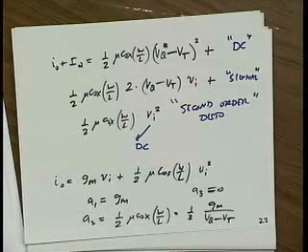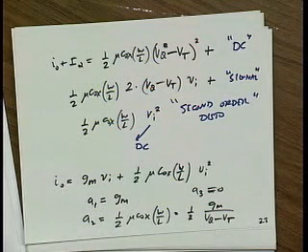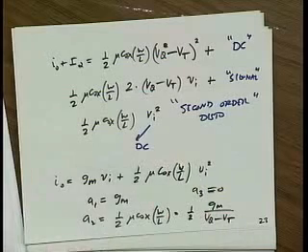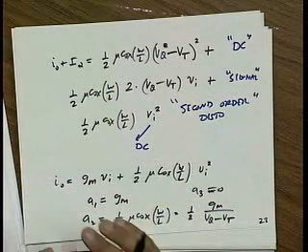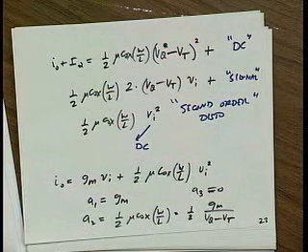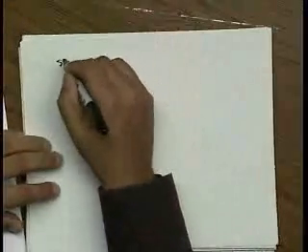We have to take into consideration diffusion current in a MOSFET. In moderate inversion, it's actually a significant contributor to the current. We have to take into consideration subthreshold devices, where it's all diffusion current. So if you look at a more complete model, including the body effect, including all the parasitics, source-drain junction, let's say parasitics such as source resistance, you find that this model is not valid. In fact, source resistance is a very important one. Let me talk a little bit about source resistance.